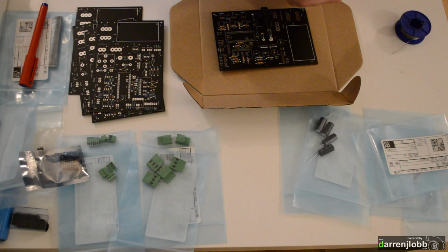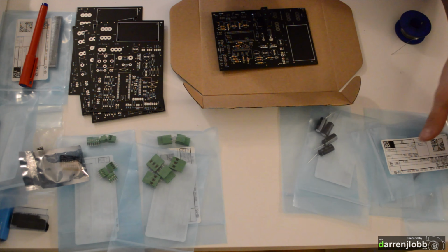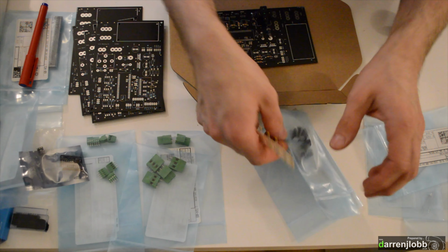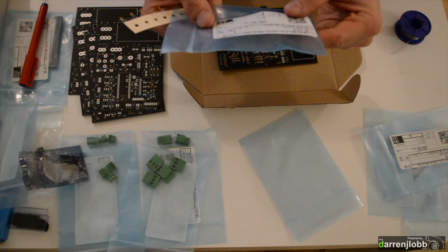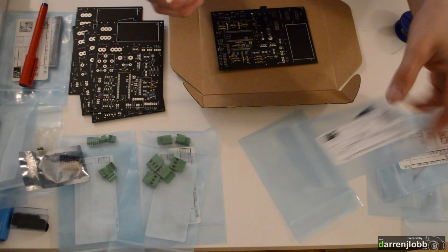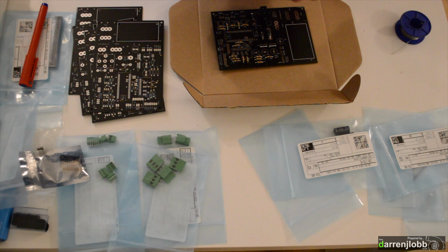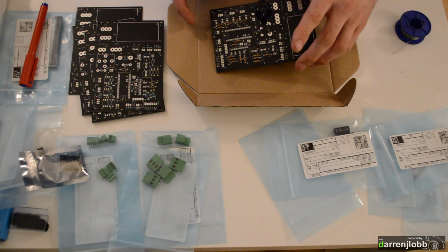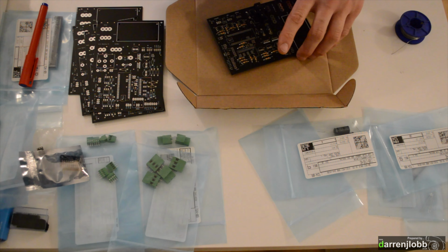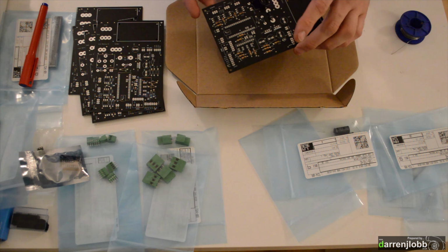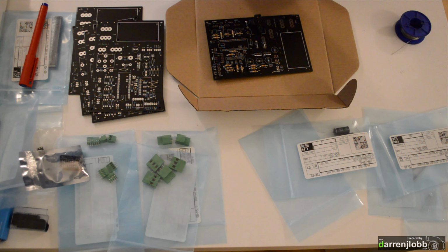Right, now we'll move on to some capacitors. We've got a couple of different types here. We've got these little 0.1 microfarad ones, and some slightly larger ones here. They're 1000 microfarad. They're marked C and then a number. C1, 2, 3, 4, 5, 6 are all of these 0.1s, and then we've got C20, 21, 22 and 23, which are the larger ones, all marked out on the board. So we'll start with C1, since it's the first one.